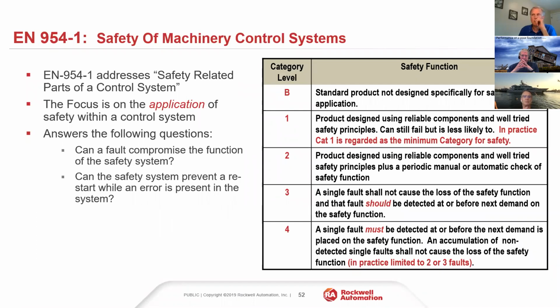So you may have also noted on that slide that 13849 kind of supersedes, if you will, or replaces EN 954. And for those who may or may not be familiar with that term, you may be familiar with what that standard introduced, which was the categories of safety. So the categories were brought up when the vast majority of safety devices were all mechanical in nature, right? So that particular standard focused heavily on how the circuits were implemented, how they were designed, and how everything played together to identify potential faults and prevent restart if an error was present, etc., depending on what level of category you were reaching.